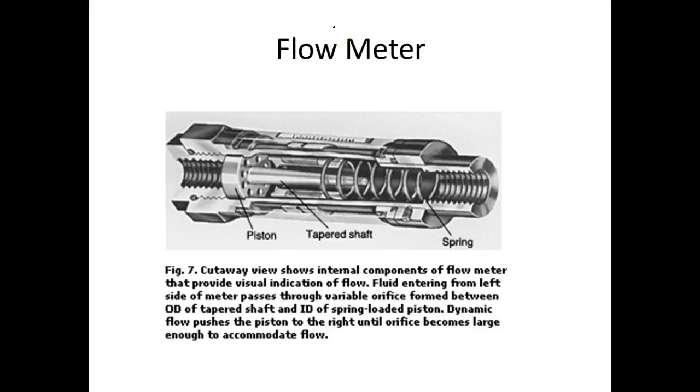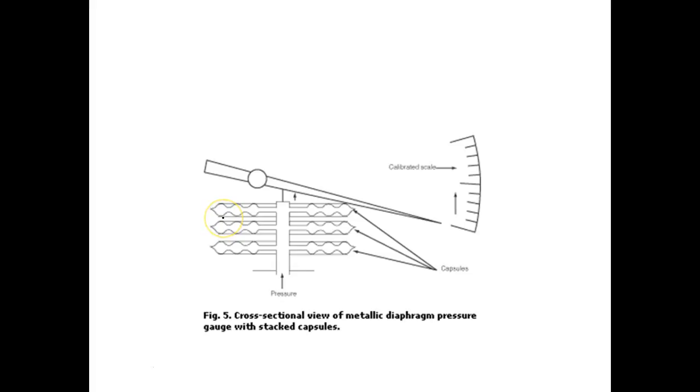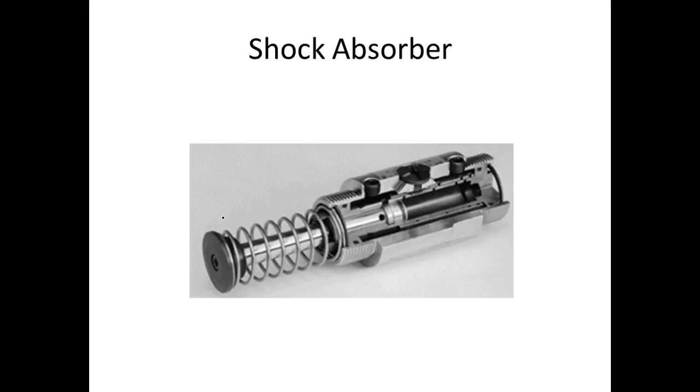And of course, there's the flow meter. We don't have any flow meters, unfortunately. Can you see how it works? It's got a calibrated spring in there. And then we put pressure in, and what is it going to do? It's going to start pushing against this thing until the force on the spring matches the force of the fluid, and then they're going to rotate that as flow, right?